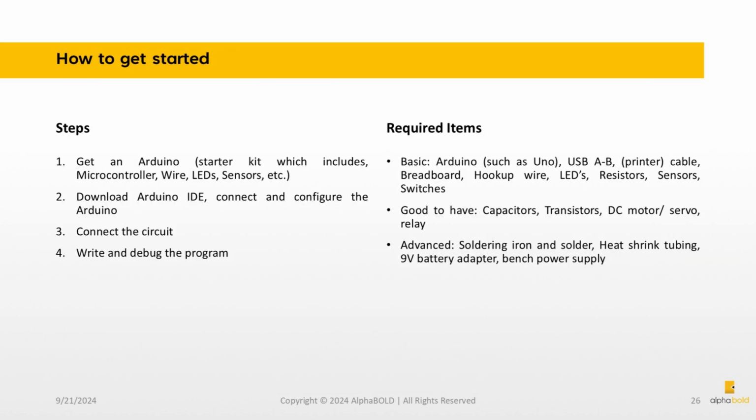How to get started? Get an Arduino starter kit, which includes microcontroller, wire, LEDs, sensors, etc. Download Arduino IDE, connect and configure the Arduino. Connect the circuit, write and debug the program.